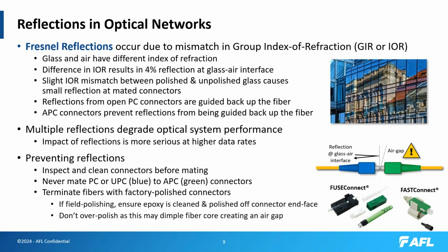And then make sure you do terminate fibers with factory polished connectors that are readily available today. You can do field polishing, but if you do, you need to make sure the epoxy is fully cleaned and polished off the connector end face, and don't over polish it, because doing so can create a dimple in the fiber core, as it's typically softer than the cladding and the ceramic ferrule around it.